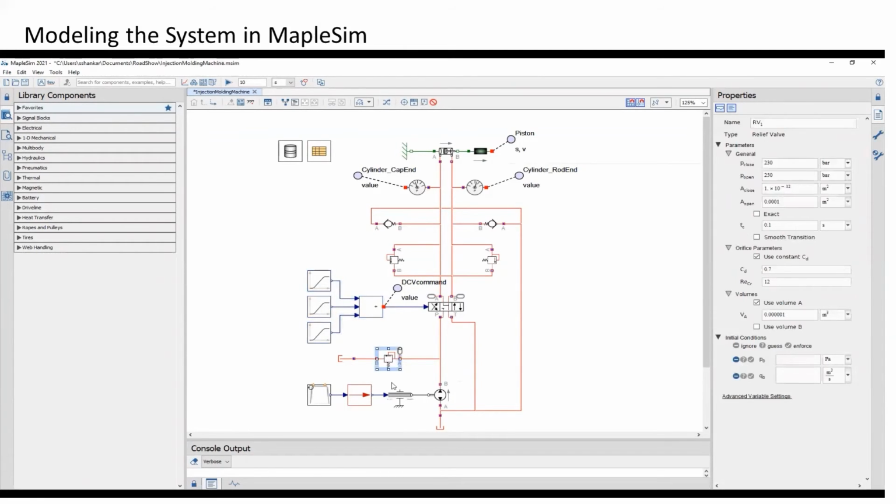In addition, you also have a relief valve there, or you can actually call it a safety valve in this case, where it is used to relieve excess pressure in a circuit. The pressure setting can be placed on the right inside those parameters.